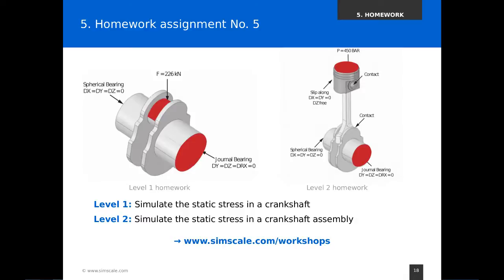And in level 2, you really try to do the whole assembly of the crankshaft, the connection rod and the cylinder head with the real pressure that is appearing at the maximum combustion, and there you will hopefully, if you do both simulations, be able to say something about whether we really need to model the whole assembly, or we can just do the simpler model on the left to have a right estimate of the stresses, for example, inside the bearing.